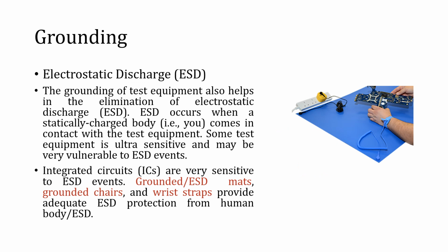Okay, coming to the next thing, electrostatic discharge. This is very important when we are handling very sensitive circuits, especially memories or CMOS based circuits. They are very sensitive to electrostatic discharge. Since we are now using polyester kinds of clothes and plastic chairs, and we keep on sitting or rubbing our clothes against the other sitting material, there is always a possibility that we are carrying a static charge.